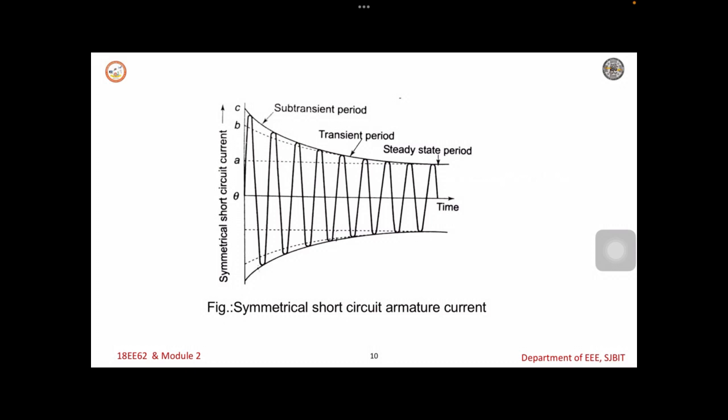The determination of the short circuit currents when the machine is on load involves the determination of internal voltages behind subtransient, transient and steady state reactances. These are the voltages obtained by adding vectorially the subtransient, transient and steady state reactance voltage drops respectively, due to the load current IL, to the terminal voltage V.